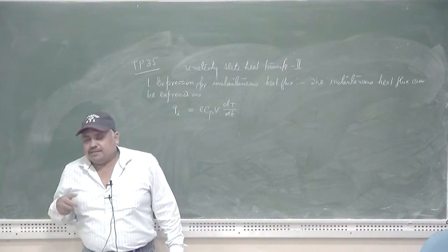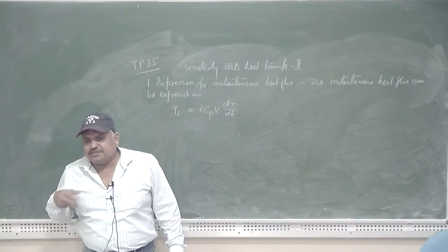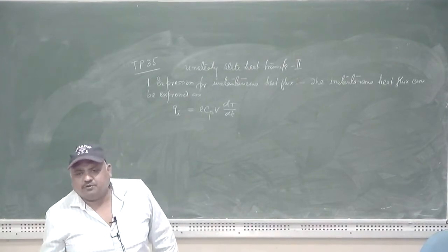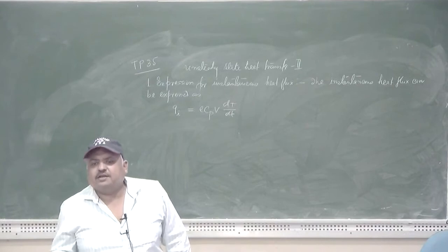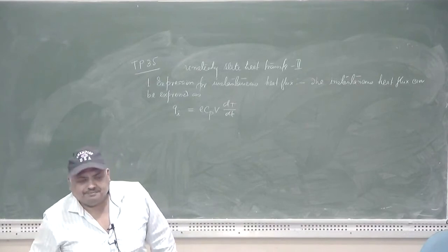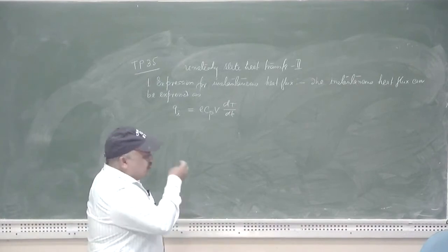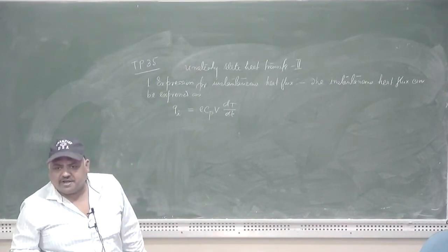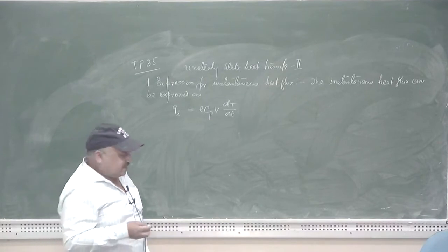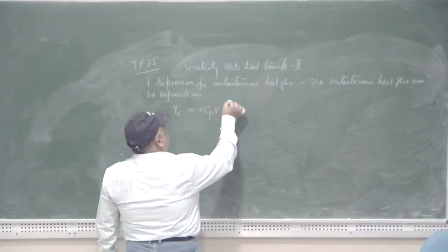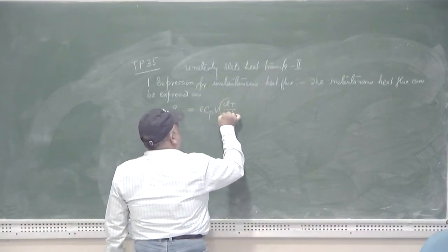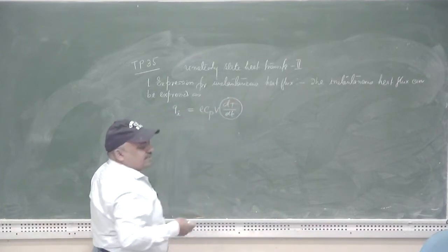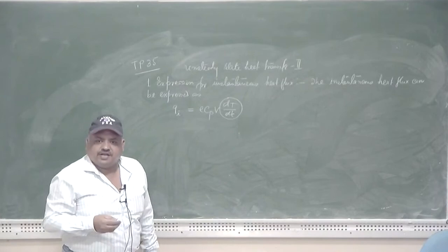So, the change in the internal energy happening inside a body is equal to the heat lost by convection to the ambient air. Because dT by dt is not equal to 0 in the case of unsteady state heat transfer, it is very important to evaluate this quantity in order to arrive at the expression for instantaneous heat flux.